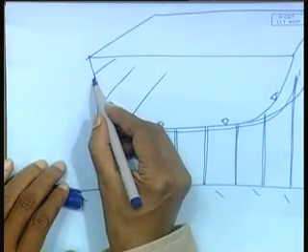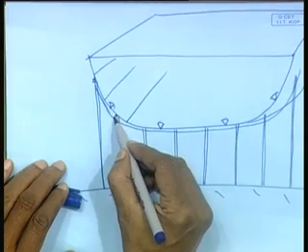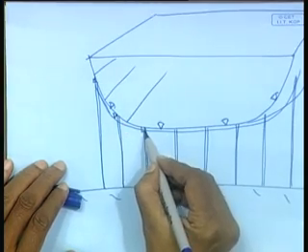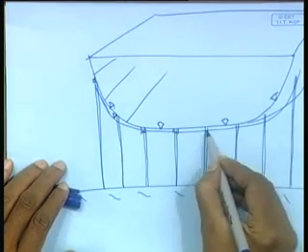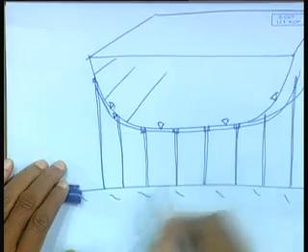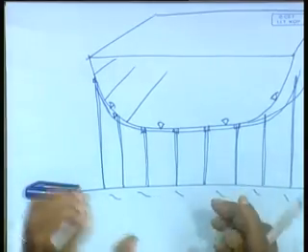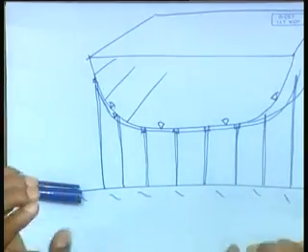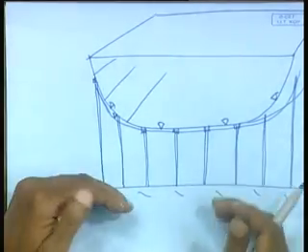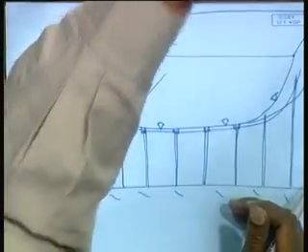What you do at the back, you put a lug and weld it, restrain it to the frame, to the skid. To the skid, you put small pieces of lugs and you literally weld the plate to the skid. You tack it, that means you restrain it from any kind of movement. Then you weld everything, so everything is fine.